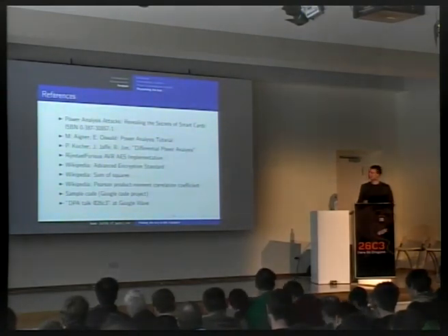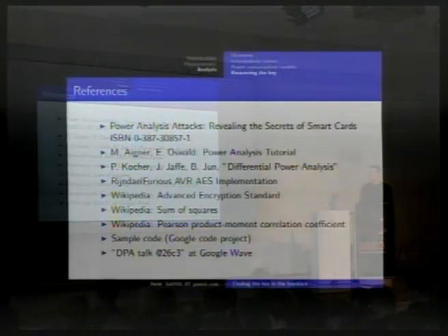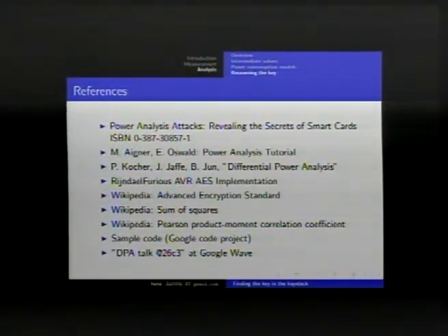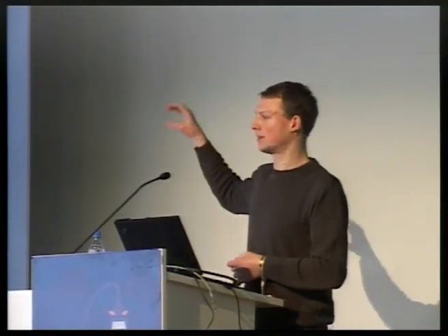One tiny note. The Hamming weight should work to recover the complete key using those samples. The Hamming distance does not work due to optimization in this code. You don't have this particular code that loads the SBox input and the output like I showed in the slide above. This doesn't work for all outputs, so you can't get any key value with Hamming distance, but Hamming weight should work. Yeah, basically that's it.